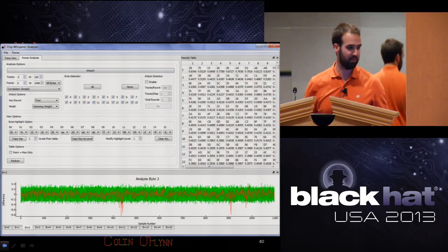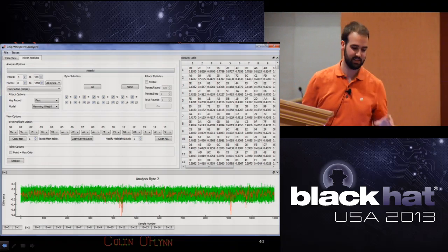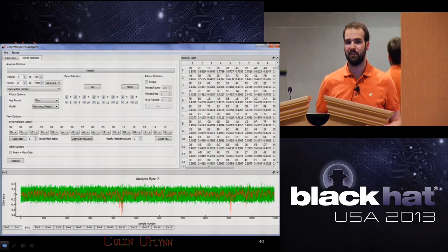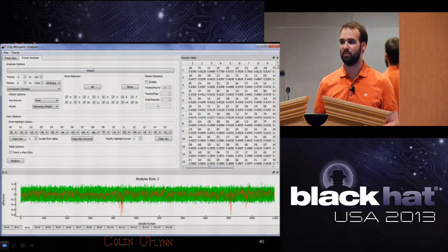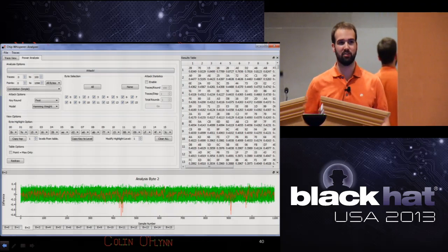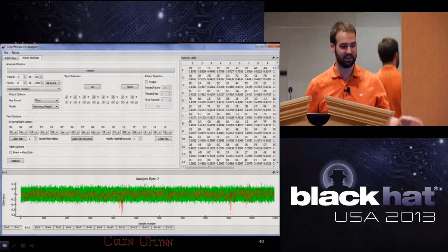So the theoretical limit of the clock speed: the ADC in this is spec'd to 105 megasamples. You can run it faster. You could overclock it; I've done 150 megasamples. You can play some games with undersampling that actually works okay. So I don't know how fast of hardware you can go. It depends a lot on what it is.